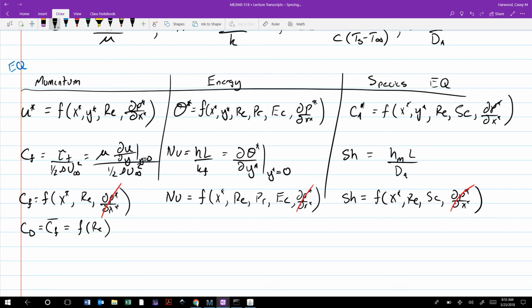If we're talking about heat transfer, this version of the Nusselt number is going to tell you what the convective heat transfer coefficient is, non-dimensionalized at a point. If you wanted to take that and find a non-dimensionalization of that h bar term, then you end up with the Nusselt number with an over bar, and because we're averaging over x, we get to drop the x star term.